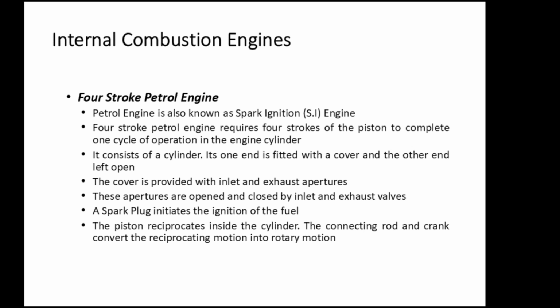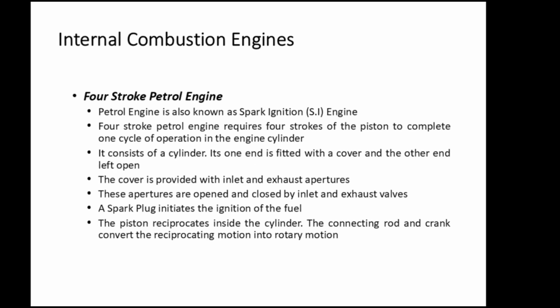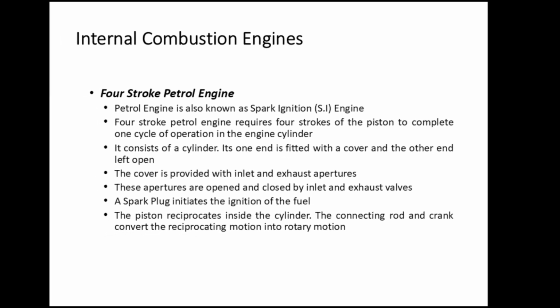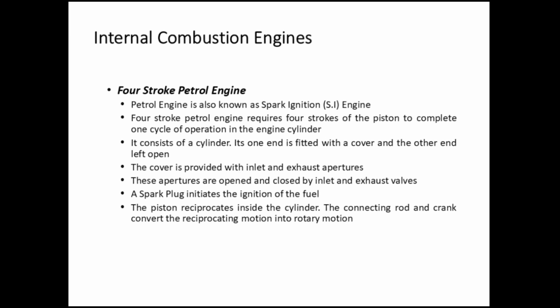Internal combustion engines. Four-stroke petrol engine. The petrol engine is also known as the spark ignition engine. A four-stroke petrol engine requires four strokes of the piston to complete one cycle of operation in the engine cylinder. It consists of a cylinder. Its one end is fitted with a cover and the other end is left open. The cover is provided with inlet and exhaust apertures. These apertures are opened and closed by inlet and exhaust valves.